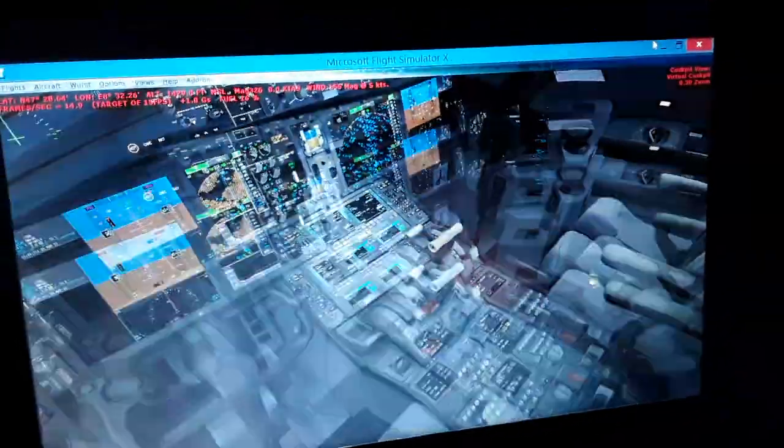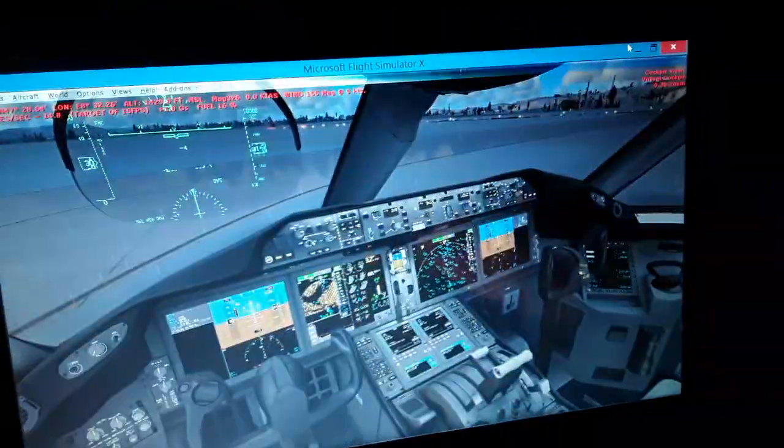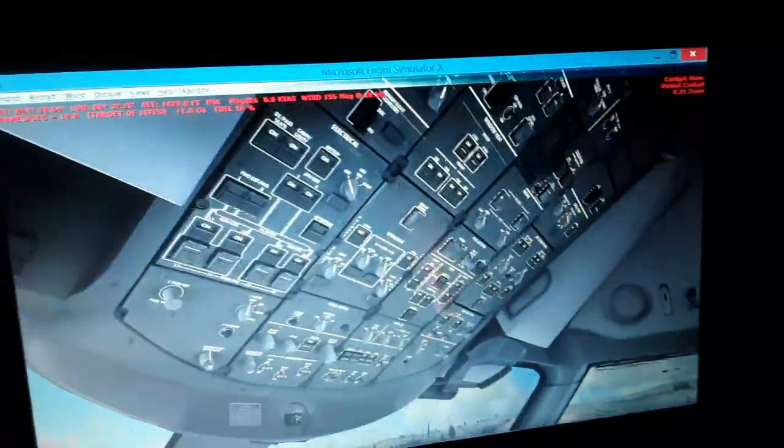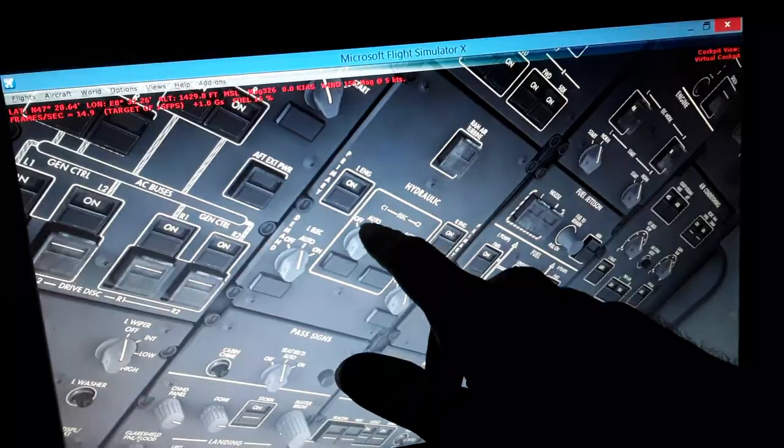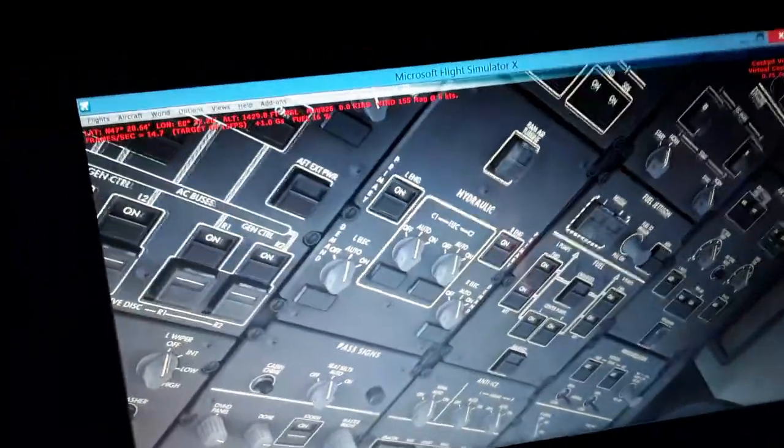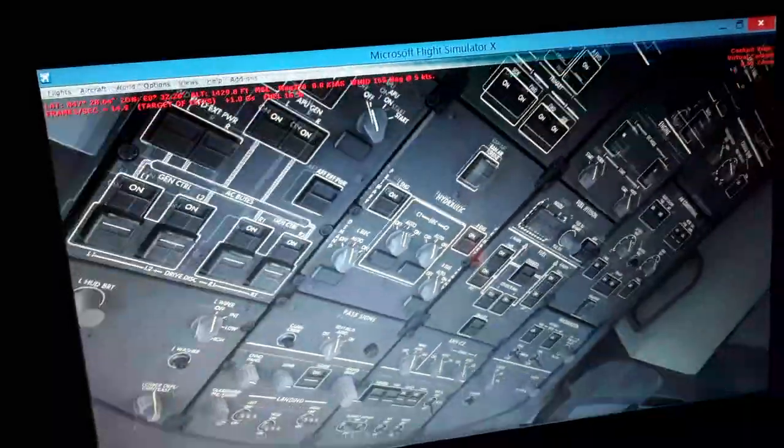So I keep showing you the flight controls. If you have a failure, as I told you, of the L2 and R2, that affects the L2 and R2 horizontal stabilizer hydraulics system over here, you have to come down here.